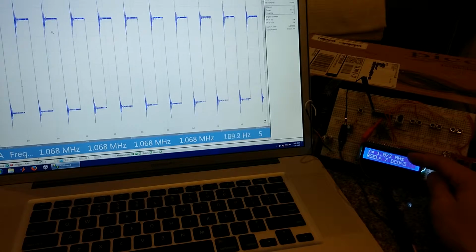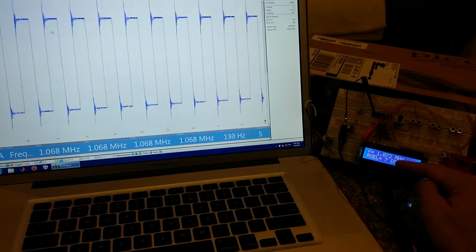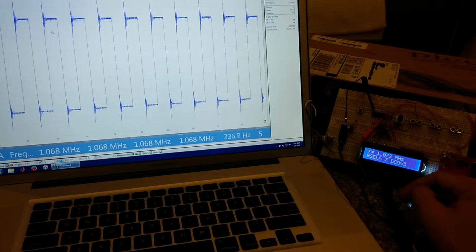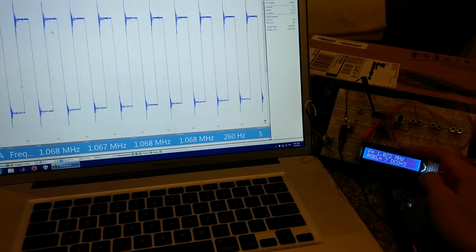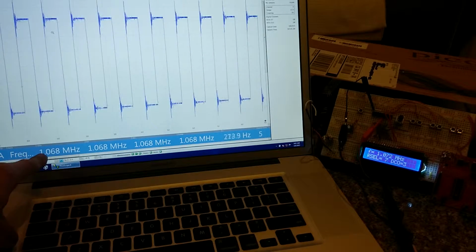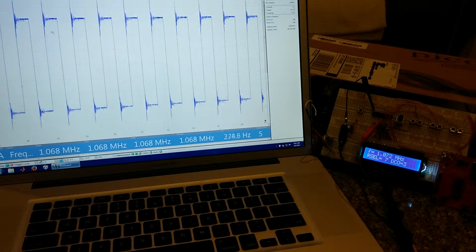The F is the frequency, and these two values right here are bit fields in the basic clock system register bits of the 2553. We have the RSEL, which I believe is the resistor select bits, and we have the DCO bits. With these specific values, we have a frequency of 1 megahertz. And with our PicoScope, we have the current value, a minimum, a maximum, and an average value.